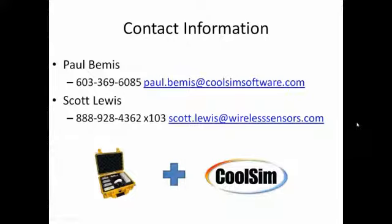Yep. Battery life of the temperature sensor? We talk in terms of years. It's 2 or 3 years, depending on how many sensors you have daisy chained from it, and what the reporting frequency is. We nominally report every minute, but in data center applications, 3 minutes, 5 minutes are not uncommon, and so you get a concomitant increase in battery life as you change the reporting interval. Just as a data point, if you had 3 sensors at a 1 minute reporting interval, 2 years is a normal battery life you'd expect.